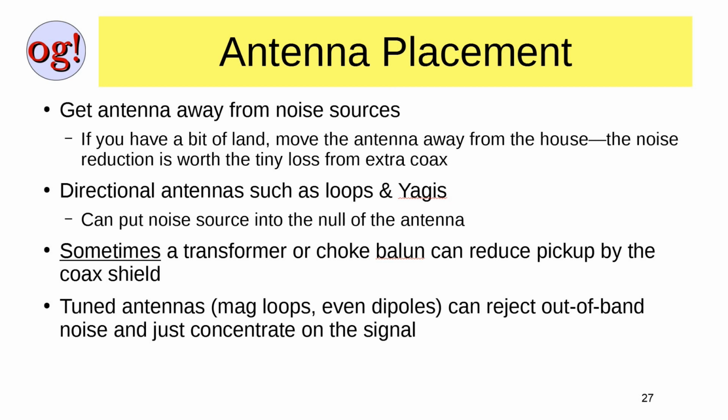Try directional antennas such as loops and Yagis. You can put the noise source into the null of the antenna. Mag loops really work well for this.